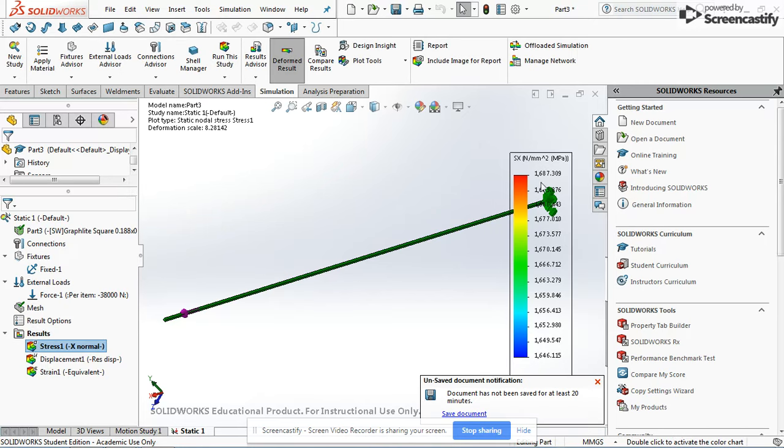We've got those showing. Now let's zoom in on the part and find out where the stress is. Now I know from previous investigation that there are some local effects at the fixed end which cause a stress increase, which is not what we care about in this case. But if you zoom in on the fixed end, you'll see the little red sections where it has some localized stress that is high.